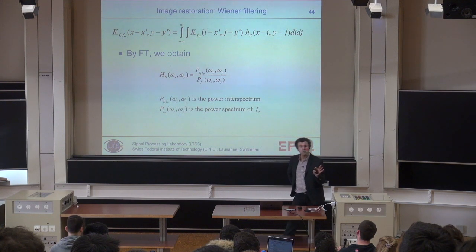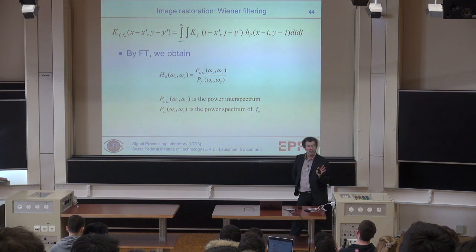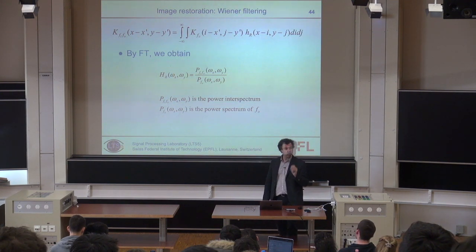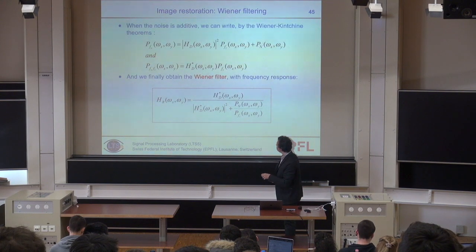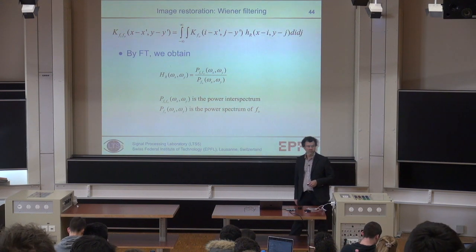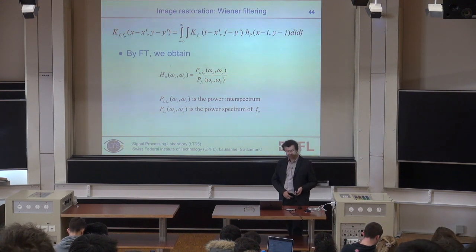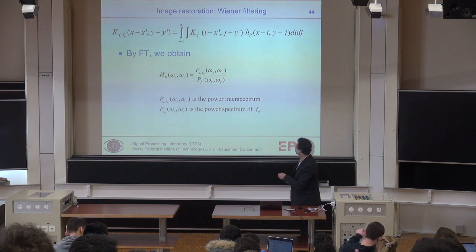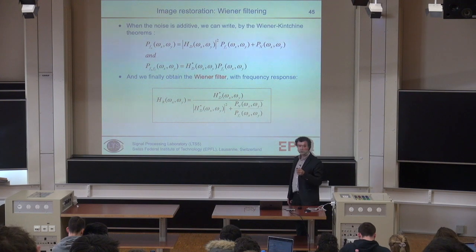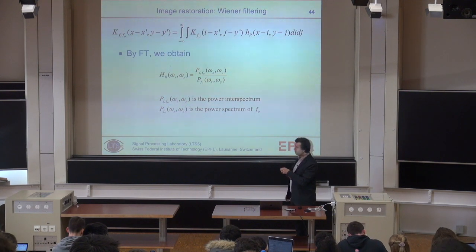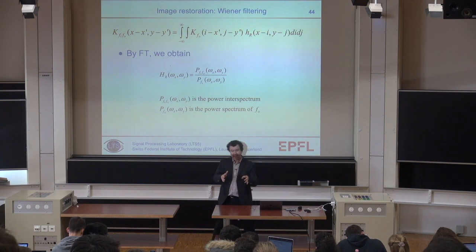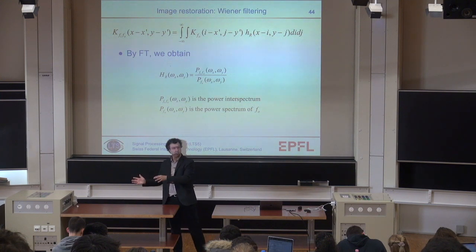But for the moment, do you see more or less how we reached there? I have to tell you how we calculate that, of course. But in terms of just the derivation, it should be quite okay. And so at the end of the day, you have an expression for the ideal filter. And then you have to use a little bit of your statistical signal processing skills to try to see what those two guys are. And you have to see that, indeed, FO is the output of a linear system where I have Fi convolved by HD plus noise.